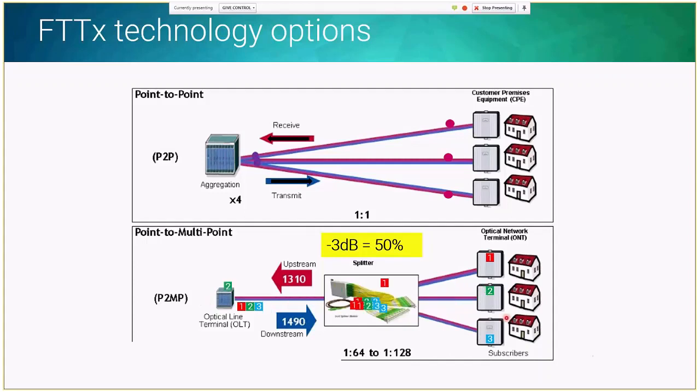If the ONT, which is the node that stays in the customer house, doesn't receive the time to speak slot from the OLT, it will never communicate back to the OLT. And we will see how important this is, especially when we are trying to measure with the power meter our loss on our network.